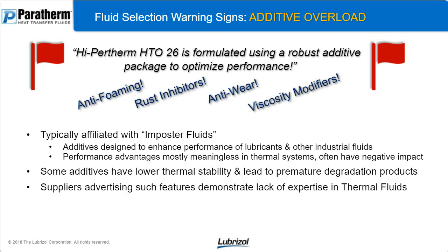Again, we're talking about supplier legitimacy and a good supplier partnership. Any supplier of a quote unquote heat transfer fluid that is actively advertising these features for their heat transfer fluid, for their thermal fluid, is demonstrating a real lack of expertise in what it takes to make a good thermal fluid, because those things don't matter. So if they're advertising it like this on the data, on the literature, on their website, that's a red flag to stay away from.